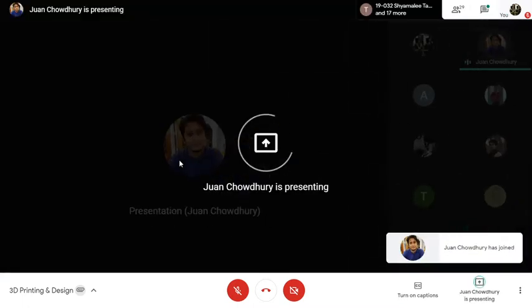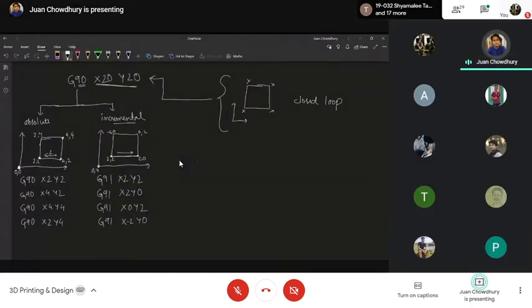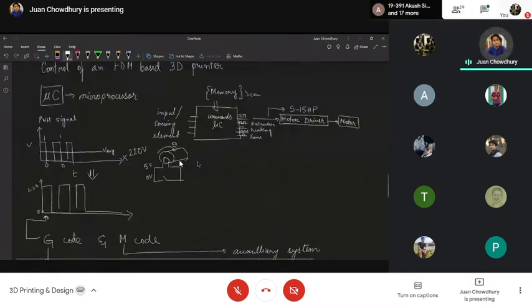So that was G code, M code. There are different codes further, but I believe once you have a look at it with a simple code, it shouldn't be a problem. With NC Viewer, you can try this particular example, and do let me know how G91 or G90 works. You can trial and error. It's pretty simple. That's very basic.